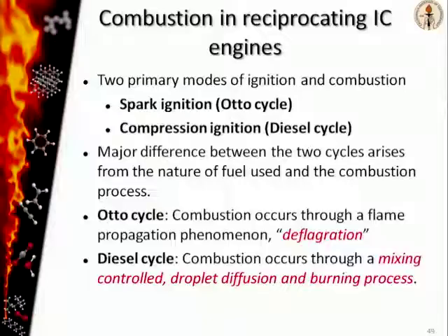In the case of a diesel cycle, instead of having a single laminar flame propagating through the combustion chamber, what you actually have is a mixing controlled diffusion and burning process. The fuel is injected into the combustion chamber in the form of droplets, which vaporize in the high temperature region inside the combustion chamber, and then you have a droplet burning phenomenon which releases the chemical energy of the fuel in the form of thermal energy.